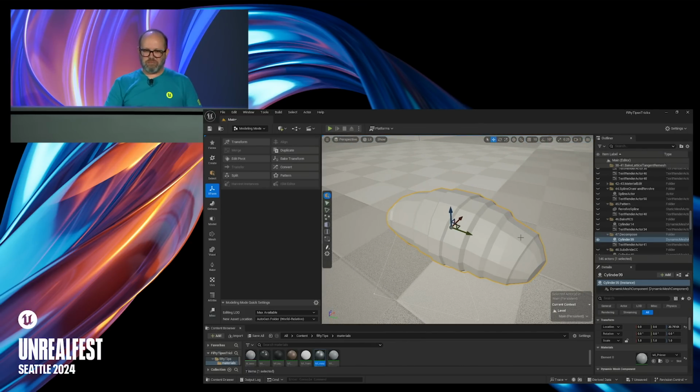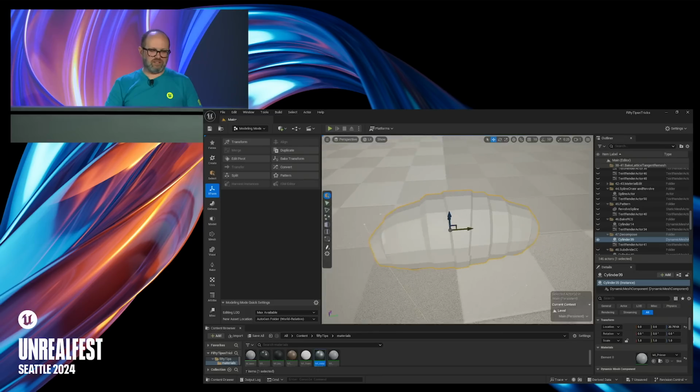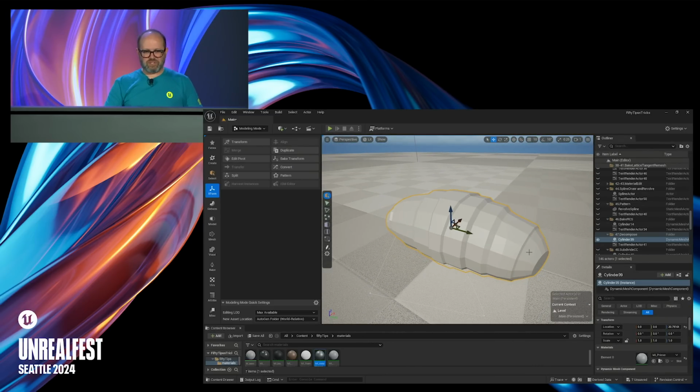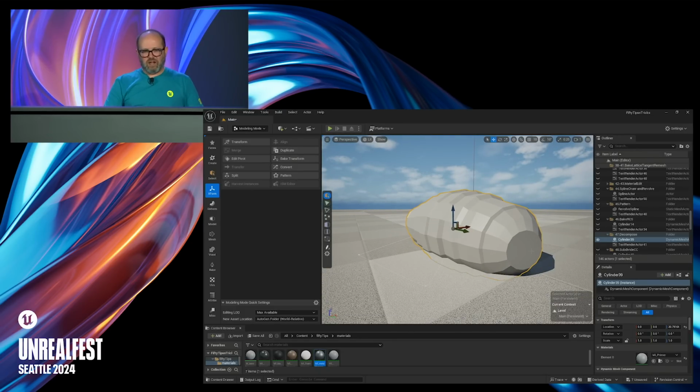Anyway, the one thing that I did want to show is, I just took a cylinder, munched it up a little bit and did a starting version of the rolls of a croissant. But one of the things that happens is that I want to use a Catmull-Clark subdivision, and our Catmull-Clark subdivision relies on four-sided polygroups in order to subdivide. And so my end cap here is obviously a bunch of different triangles.